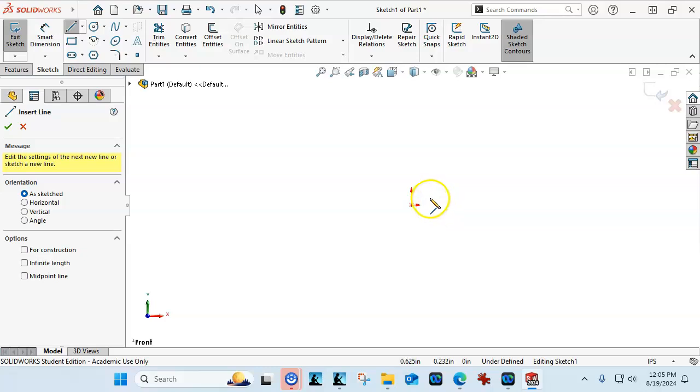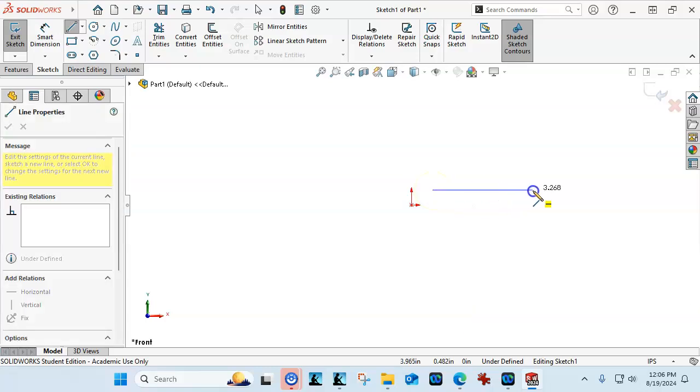And I want to illustrate the snap, so a little bit of a jump, and then the little yellow box pops up. This is one of those I'd really like to zoom in on, but I don't think I can hold this position in the software and do the zoom. So what I should do is click on the origin, and then as I drag away, I'll start to see the line. If I click away or I miss the origin, it does not go fully defined.